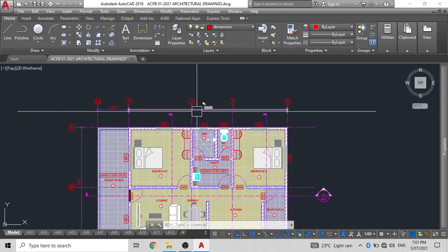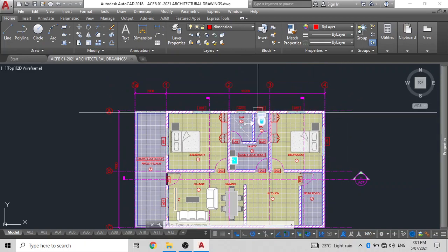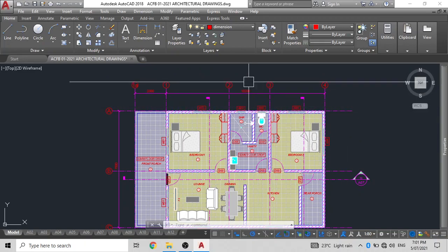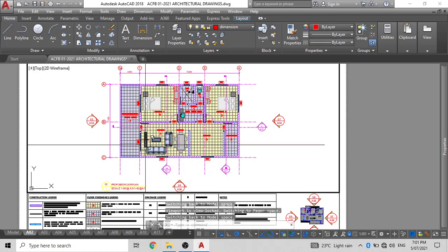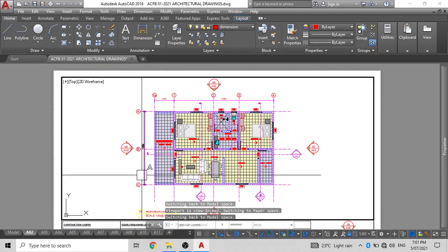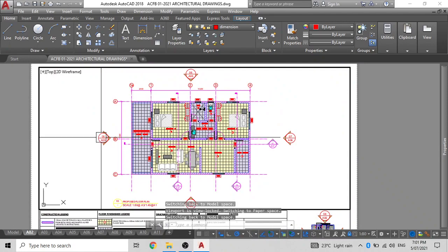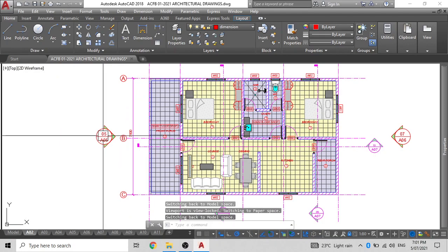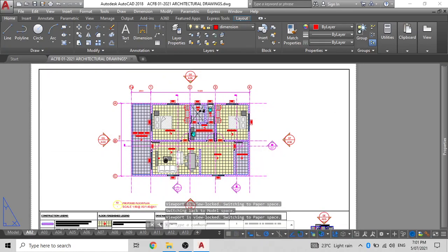So now these are all the dimensions that you actually need in a floor plan, and let's check it out. Let's check how it looks on our model paper space. So my paper space is A02, and as you can see that over here that floor plan is actually shown properly. I have set up the key. These are the elevation key. This elevation is of this drawing number and will be represented on this sheet. Similarly with the others, as you can see that everything is in check.